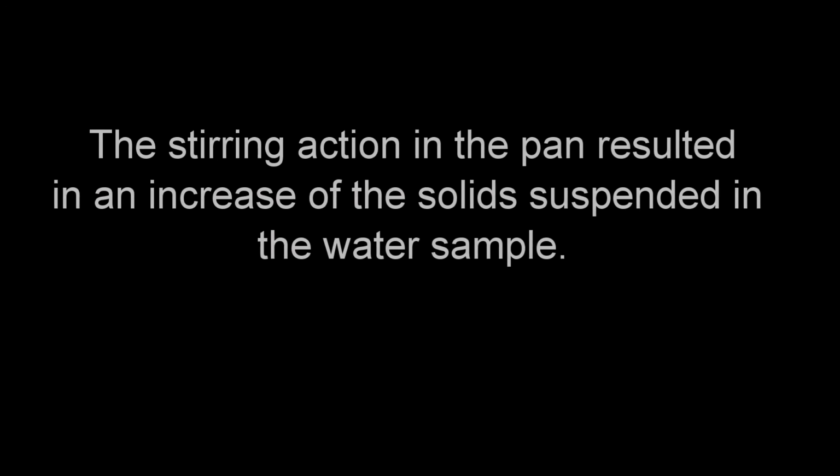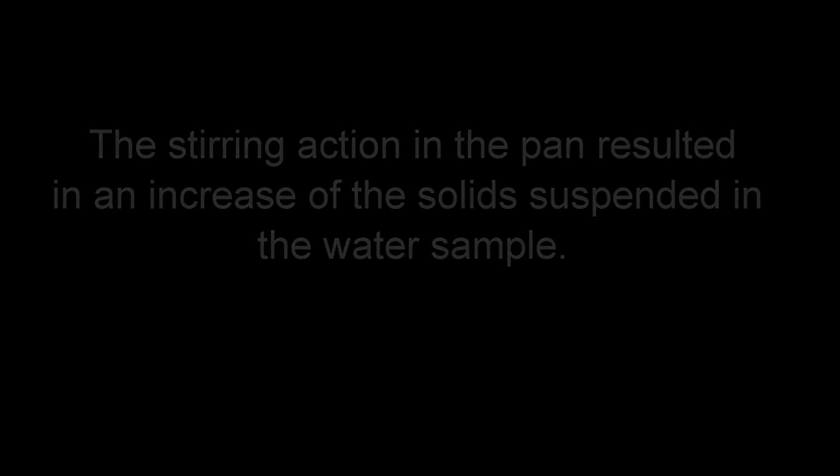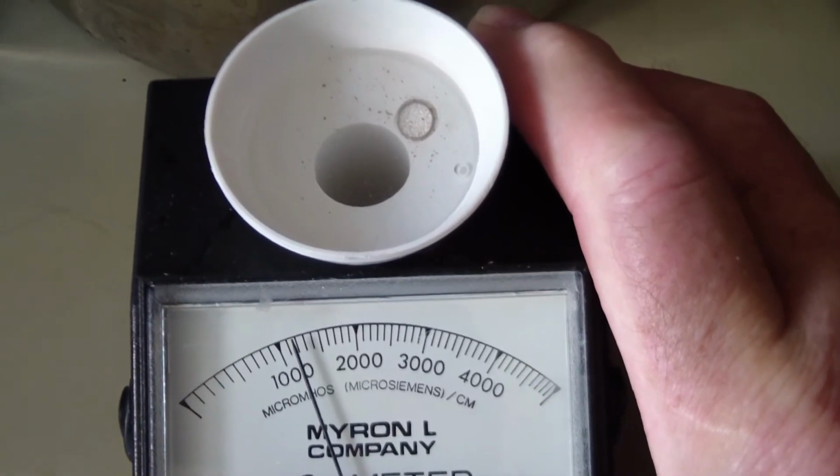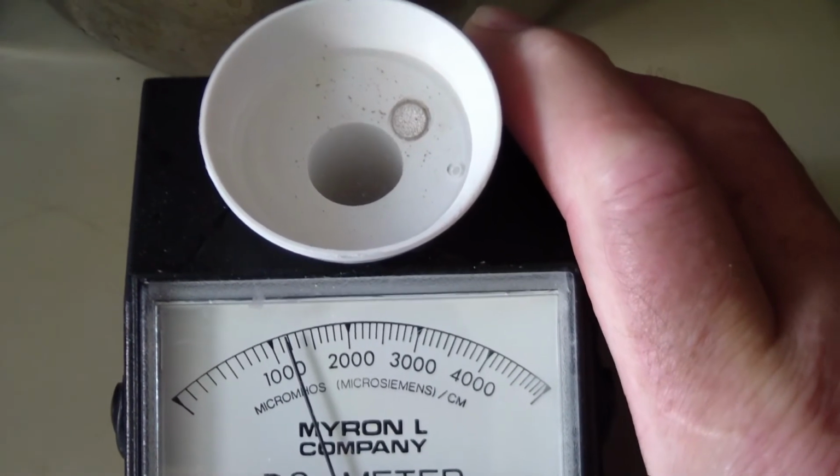The natural attraction of these solids to the intense heat being applied to the pan hold a portion of the missing particles in a thin layer. Other particles are deposited above the water line as the water sprays outward from the bursting steam bubbles. This is the exact process that goes on within a boiler.